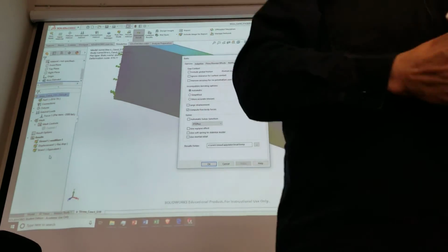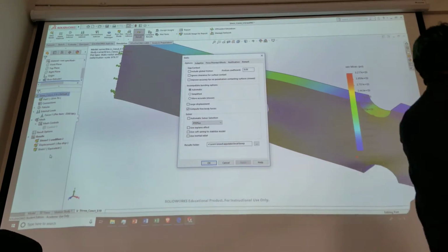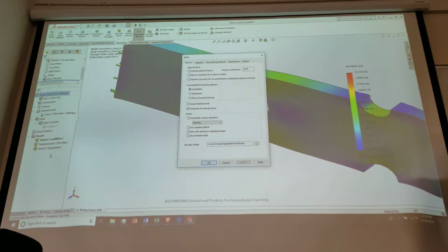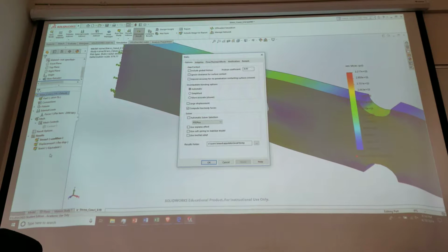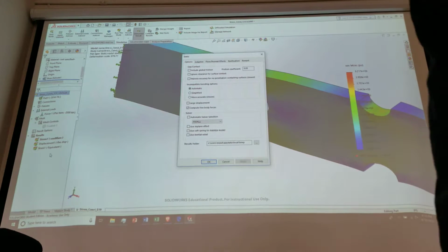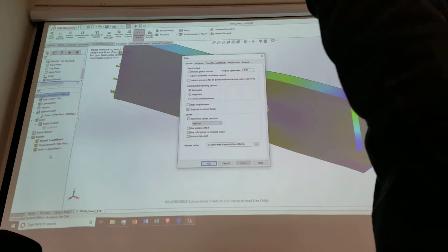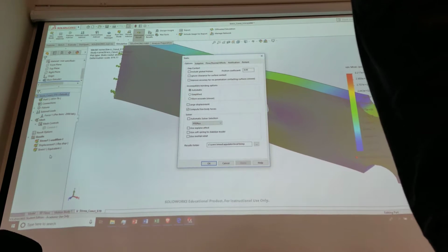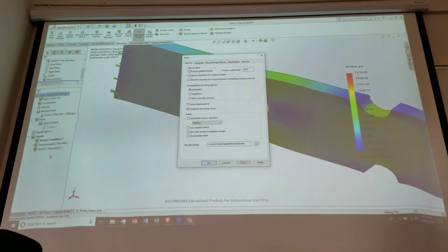So we make this out of some nice rectangular cross section, which gives us our I, that gives us our c, or a circular cross section. Doesn't really matter, or even some other shape, as long as it's constant, the I is constant. We can make it any shape we want. But guess what? M is a function of where the force is applied, how far the force is applied. Well, if we load it up, what happens to this beam? It bends.